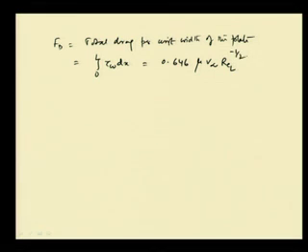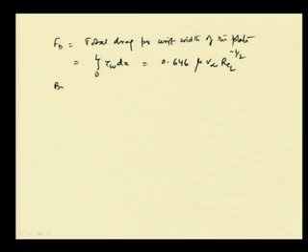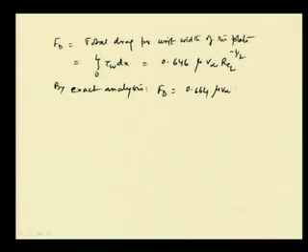So, REL is the Reynolds number based on the length of the plate, and by exact analysis we got this value as FD equal to 0.664, just a little difference, mu into V infinity into REL to the power minus half.